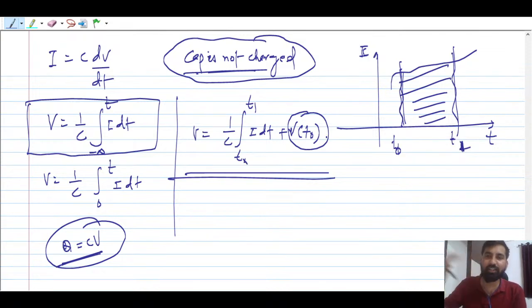So when there is a current and it is going to charge the capacitor, guys, when current is going to flow, if the current is finite, your voltage cannot change immediately, right? Matlab, suppose voltage is 0 across the capacitor, and the current has started flowing. So you can't say that the voltage will be 12 volt directly. No, okay, the voltage will be 0 only initially, right? That you have to always accept.